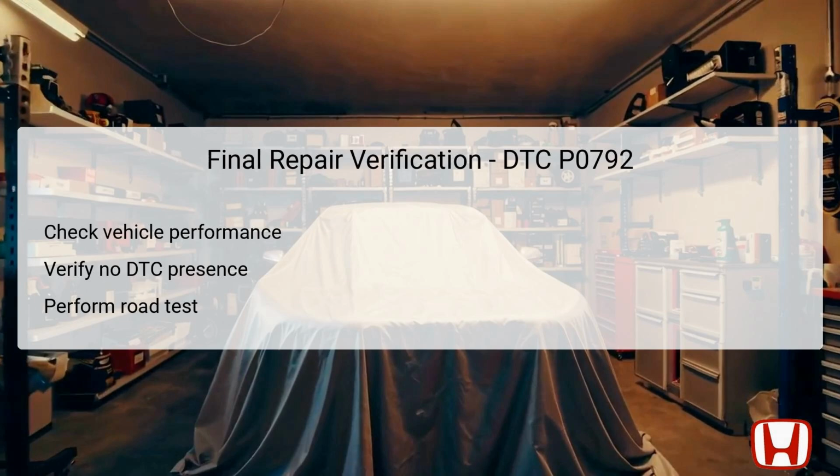Final repair verification is critical for ensuring that the DTC P0792 issue has been effectively resolved. To confirm successful repair, check the overall performance of the vehicle, paying close attention to transmission behavior, responsiveness, and engine performance. Also, use the HDS to ensure that no DTCs are present in the system following repairs.